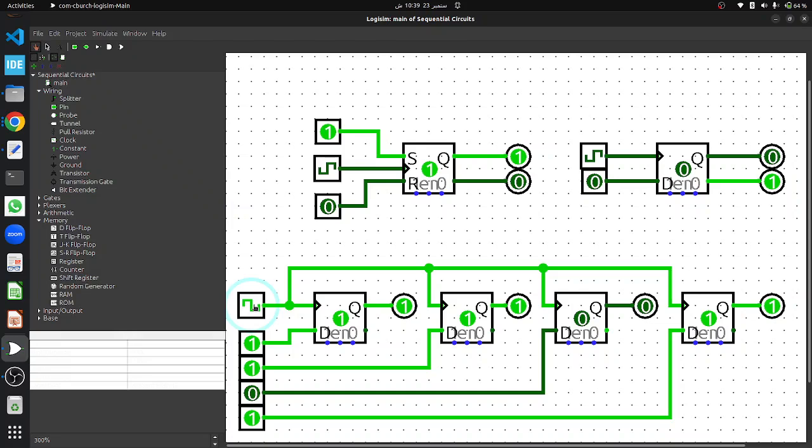Now let's change it back to the falling edge and change the input to 1010. Here you can see that on the falling edge, nothing has happened, none of the outputs get changed. Let's toggle the clock back to the rising edge, and here you can see the output is updated with our new pattern, which is 1010. Now let's enable the ticks enable to keep the clock toggling continuously, so we can change the input pattern at runtime and see the changes occurring.